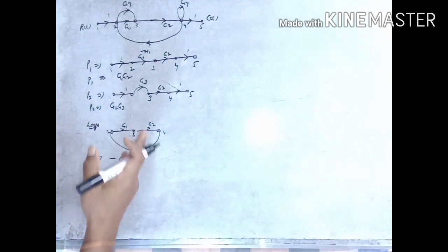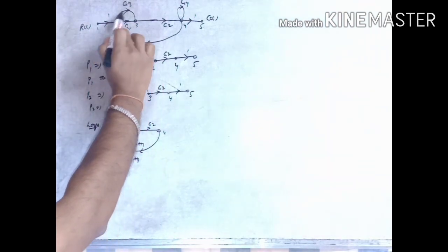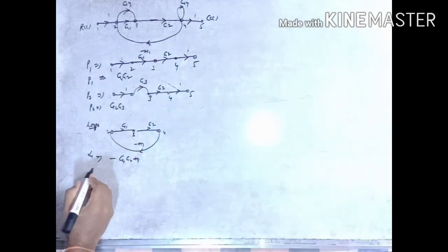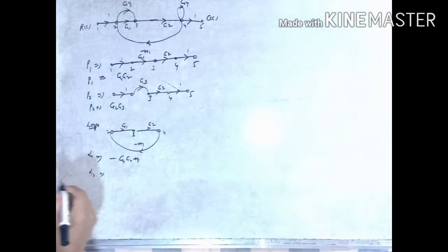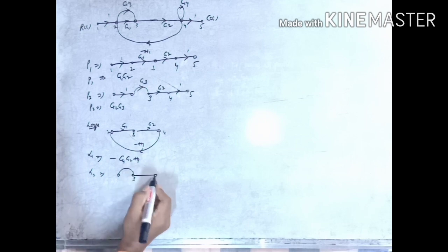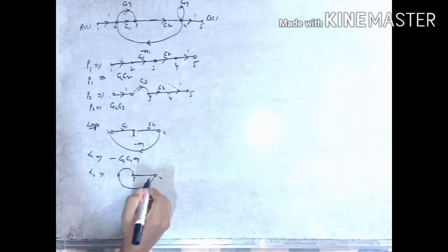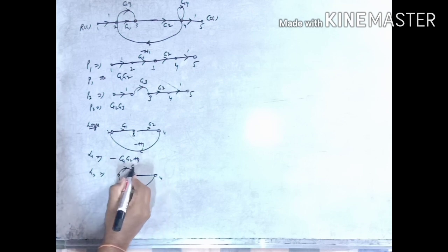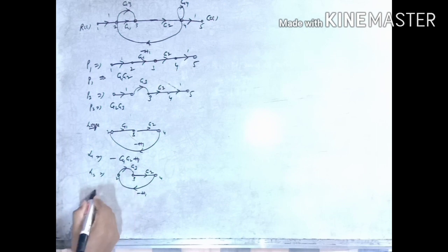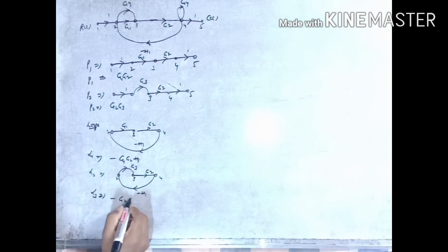Next, identify the remaining loops. 2, 3, 4 again coming to 2. So this is also one more individual loop. That is 2, 3, 4 again, H1 minus H1, G3, G2. So write the product of these gains: L2 equals minus G2, G3, H1.